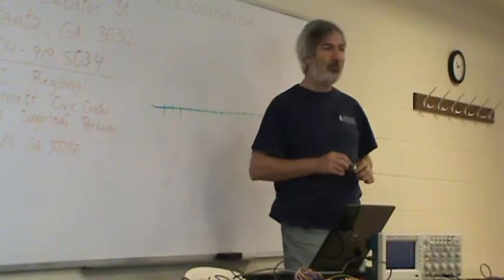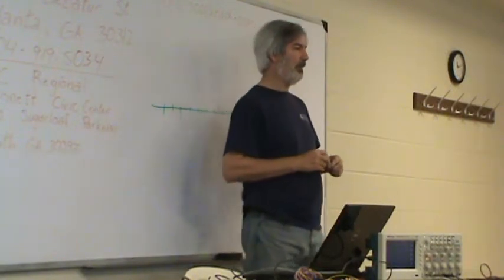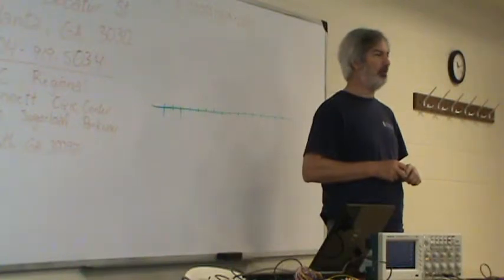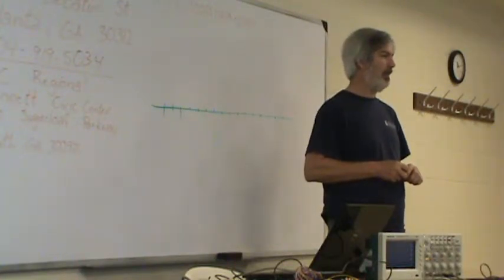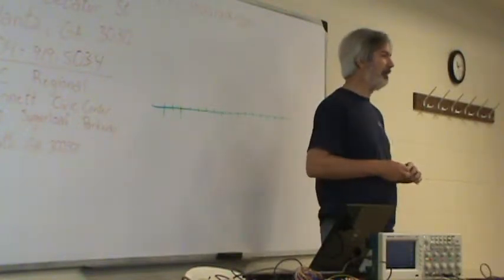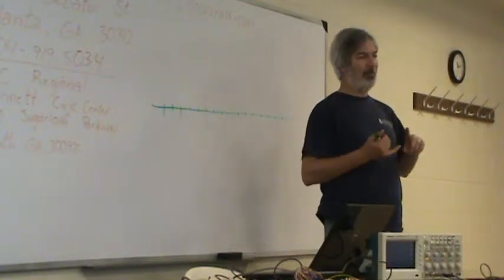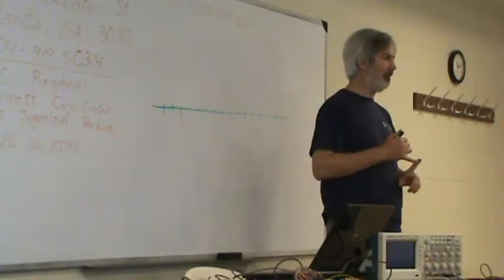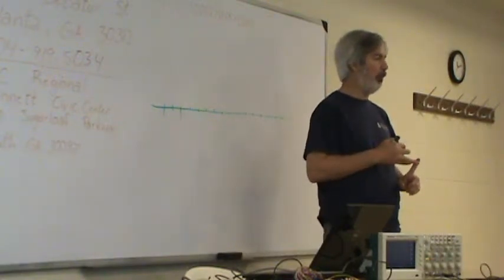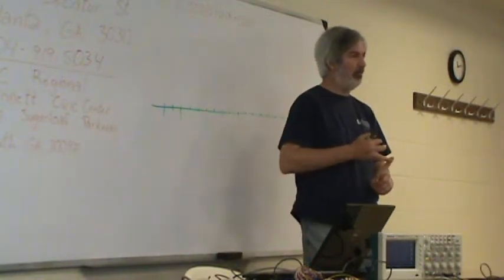A lot of times what you'll find is, for example, you've got some serial communications that you're trying to do, and it simply isn't working. And there's a number of different things that may be wrong. You may have your transmit and receive lines reversed. You might not have gotten the serial ports set up, so you don't have any signals at all.